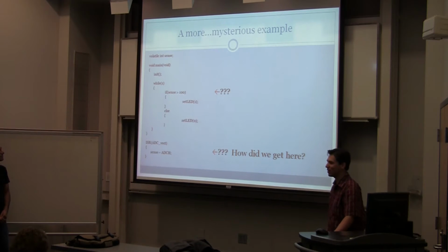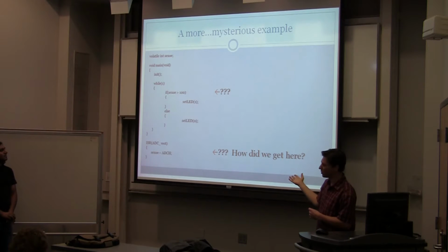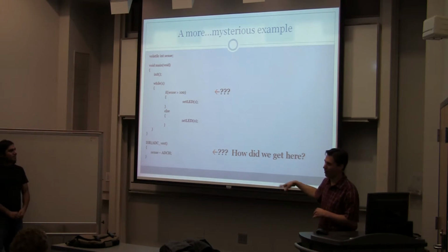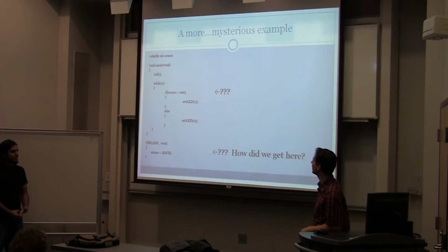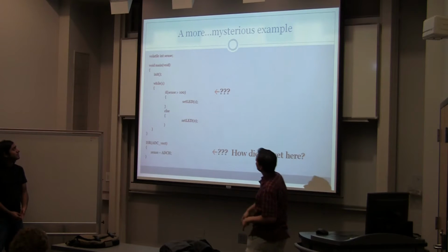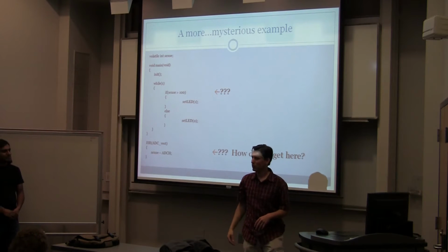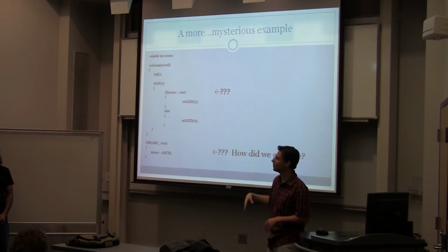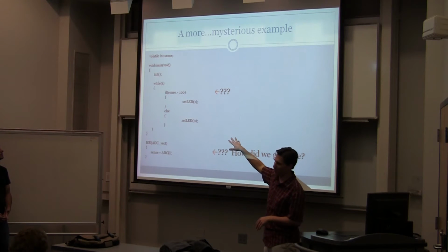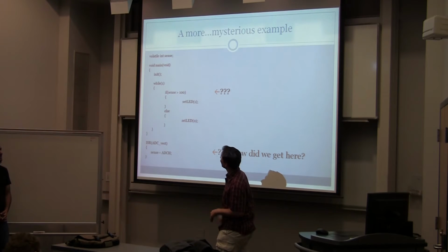Okay, but here's something a little more mysterious. And this is, again, the use of interrupts. And I'm just using analog interrupts because you're somewhat familiar now with the analog system and what's happening. So we have declared way up at the top a global variable, which means that this variable can be accessed in main and also in other functions. And it has an interesting keyword in front of it called volatile, which I'll talk about in a minute. But just notice that it's there.